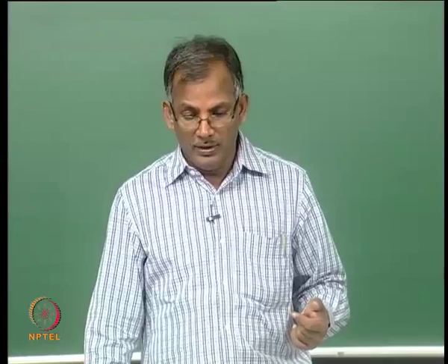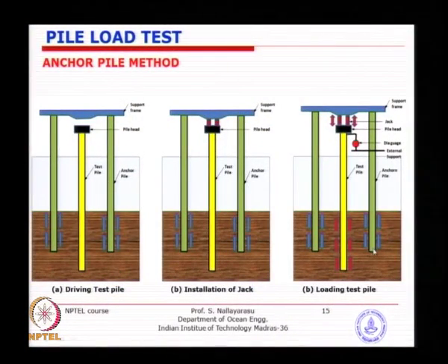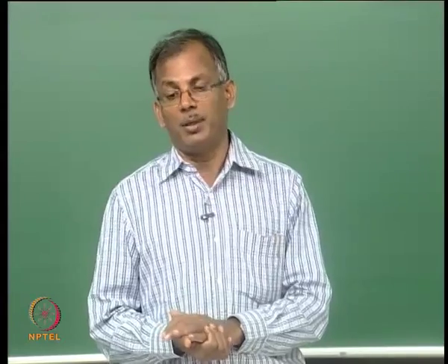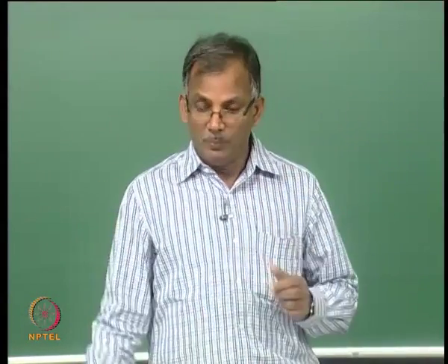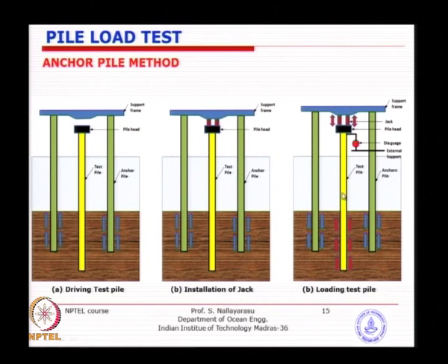At least this pile has the end bearing, whereas the anchor pile will not have the end bearing. So, you need to have sufficient penetration. Sometimes it may become very large, bigger than the test pile, because you need bigger capacity in tension than the test pile, which is being tested for compression capacity. So, you have to be a little bit careful.